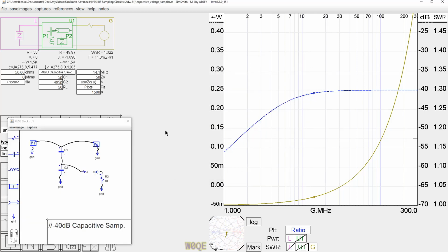But at low frequencies, where these impedances start to rise, the combination of these is no longer low enough to drive 50 ohms, what we start to see is a drop-off in coupling. This drop-off in coupling means you have to compensate for what frequency you make a measurement at if you want to do harmonic measurements. We can play with this circuit some and make it a little bit better.